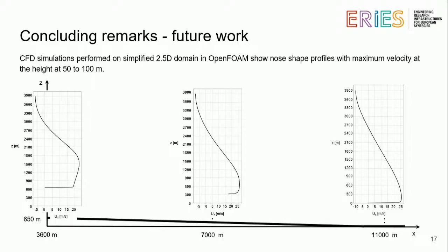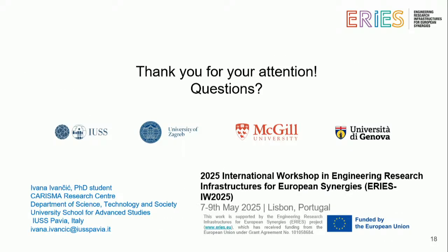Obviously, I forgot to tell you, I'm working with OpenFOAM, running RANS. So it's not time dependent, which is one mistake I'm working with knowingly. Then I still don't have exchange of temperature between the atmosphere and the ground. That's another mistake I'm aware of. And I'm using Boussinesq approximation, so the change of density due to temperature is insignificant in this case, only when we are multiplying it with the g. So that's all from me. Thank you for your attention.